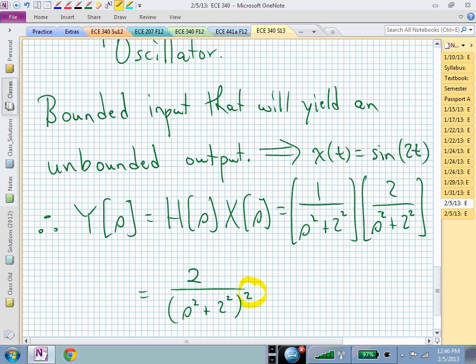It's constant with 1. If I gave you an output in the Laplace domain, Y of s equal to 1 over s squared, what's that? That has that t, doesn't it? That's a ramp. So every time you increase the power in the denominator for that factor, you're incrementing your t in the coefficient of your expression.